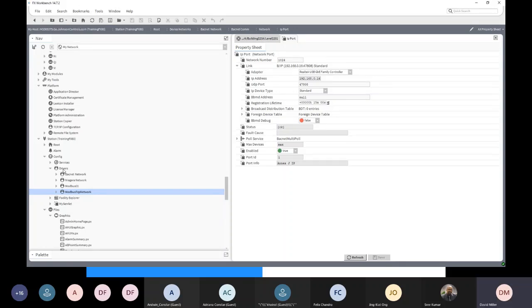Yeah, so the point count matters, the device count matters, and whichever limit you hit first is the limit that matters. But you can also have a situation where you've got a Daikin VRF system with a single BACnet connection and 1,000 points, and then you might have 20 M-bus meters where you're only reading 1 point out of each meter.